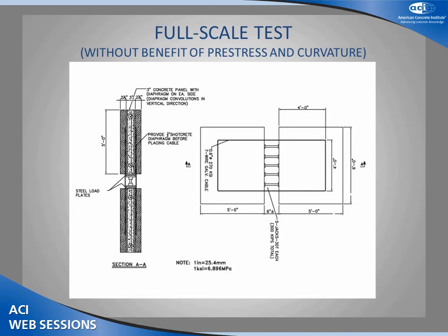Why? Because there are three very important things here. First, what is missing is pre-stress. A normal tank has spirally wrapped pre-stress wires, and that provides tremendous clamping force in this direction, and that is missing. The second is the confinement effect due to the pre-stressing wire.